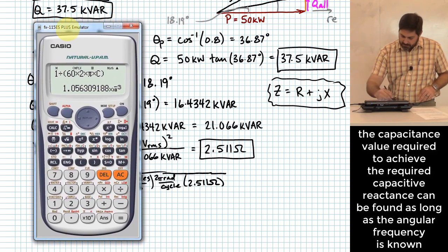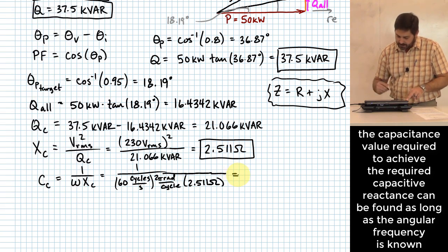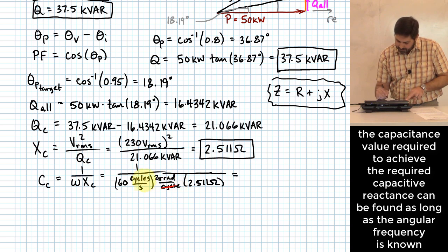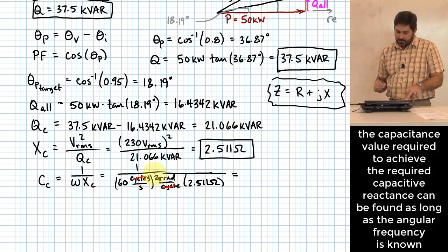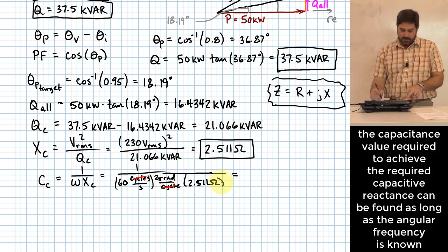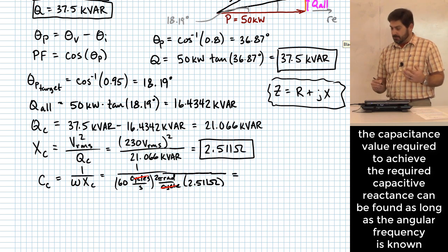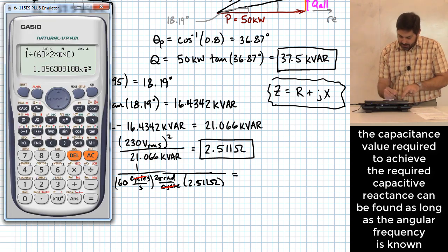Now, what comes out of that calculation units-wise? Okay, think about what we're doing here. The cycle cancels the cycle there, right? Radians is not really a unit, and we basically have in the denominator ohms over seconds, right? So the reciprocal of ohms over seconds is seconds over ohms. And what is seconds per ohm? Seconds per ohm is a farad. So what we have with this is